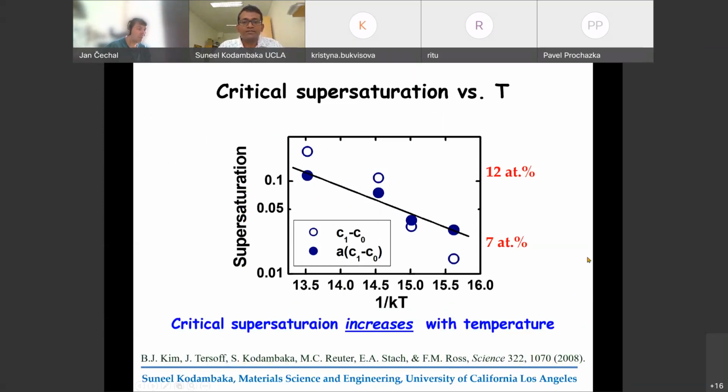And thermodynamically, you don't expect to have any supersaturation, because right after it crosses the liquidus line, you should expect to see crystal formation. But in reality there is always a nucleation barrier. And so to overcome the nucleation barrier for the crystal, supersaturation is a consequence of that.